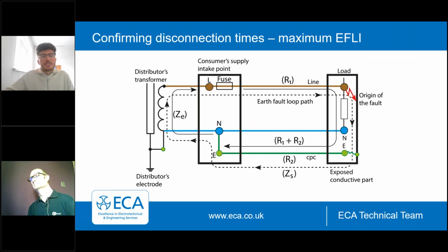Okay, so how is it that we confirm these disconnection times? How is it that we know we are actually achieving the required disconnection? So we generally do this by confirming the maximum earth fault loop impedance for the circuit in question. So what is earth fault loop impedance? Now we've got on screen here an image which should aid to describe this. The earth fault loop impedance is the impedance of the earth fault current loop starting and ending at the point of earth fault, and this impedance is denoted by the symbol ZS.